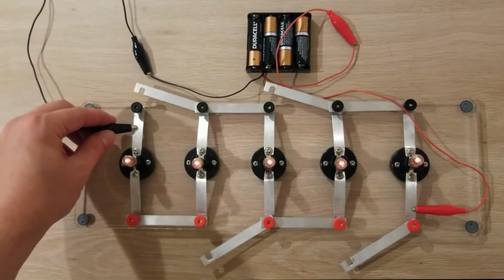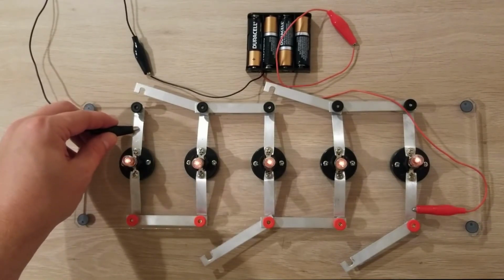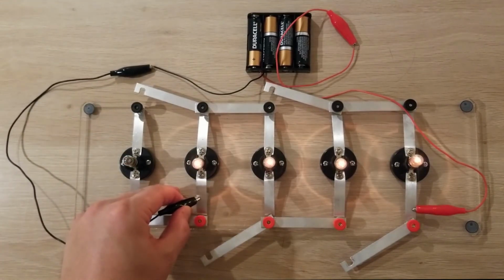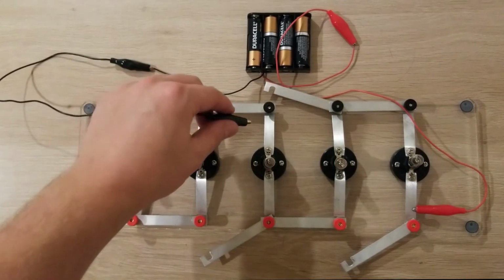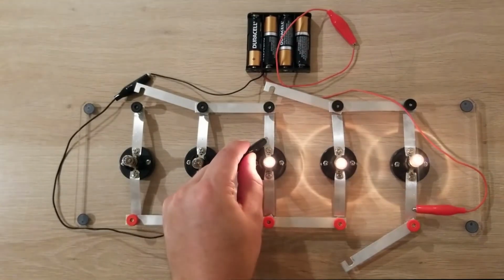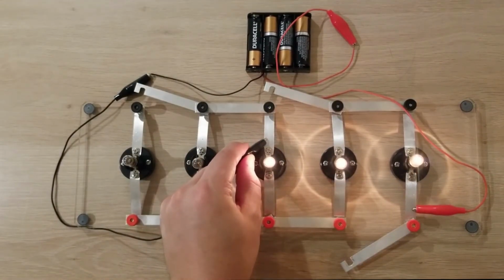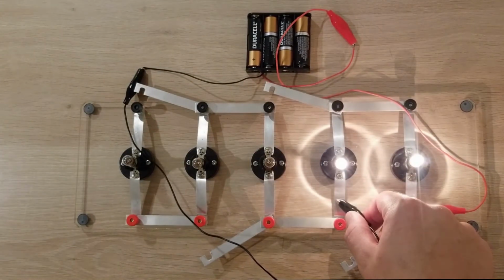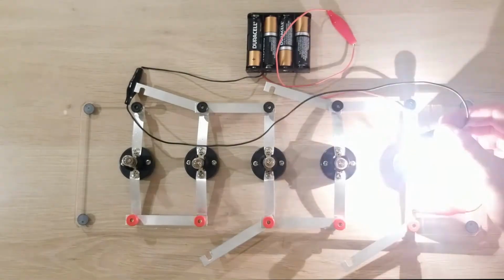Here, I start off by creating the largest possible series circuit on this board, and I gradually reduce the number of bulbs in the circuit by one at a time. Notice that the bulbs get brighter as the circuit gets smaller. This is because voltage is divided among each resistor within the circuit. Since the bulbs all share the same resistance values, the voltage of the supply is evenly divided across each bulb.